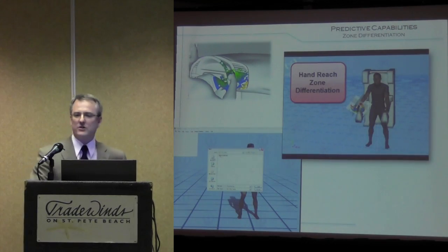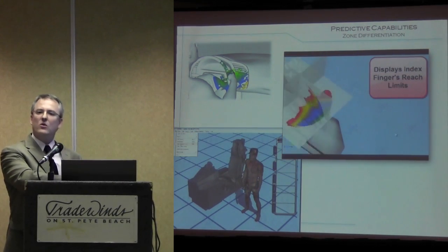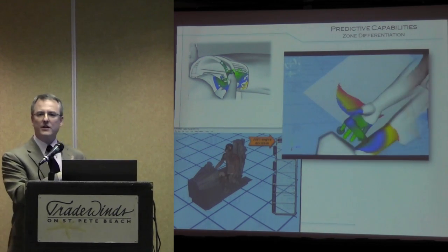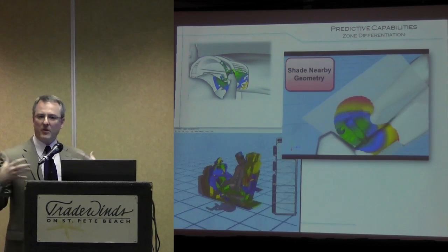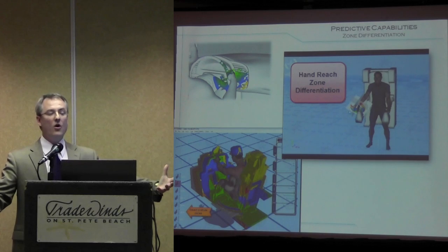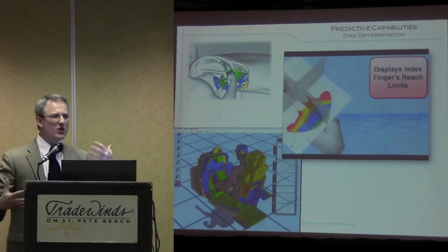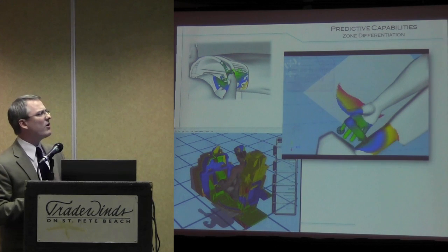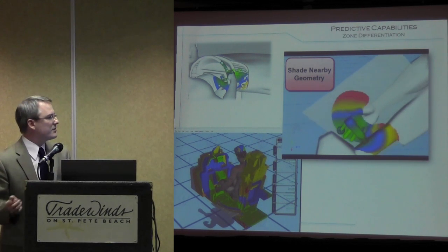In terms of the performance measures, this is, I think, a very powerful ergonomics tool that transcends the typical reach envelope. So not only do I show you what you can and can't reach, but I show you the green zones. What are the most comfortable areas to reach, say for fingers or for your arms, and your body and your legs. I then take that information and impose it perhaps on existing geometry. Or I just look at around the avatar if I'm way high up on the design stream and just starting to try some design concepts. We call this zone differentiation. It's a very powerful ergonomics tool for upstream design, but also for downstream analysis.